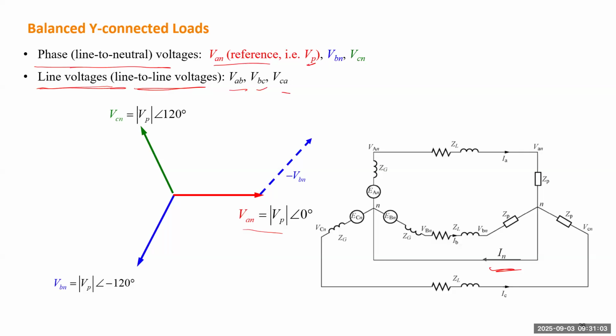So in the circuit, when you write down the voltage phasors, pay attention to the subscripts. For instance, when we call it VAN, both A and N have purposes, because VAN represents how much the A side is higher than the N side.